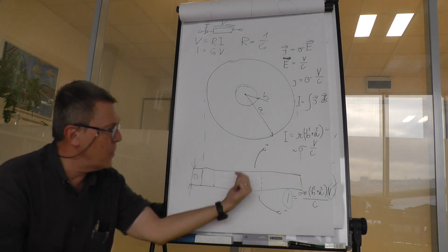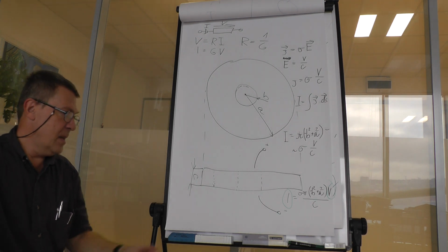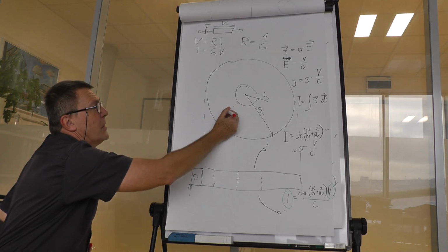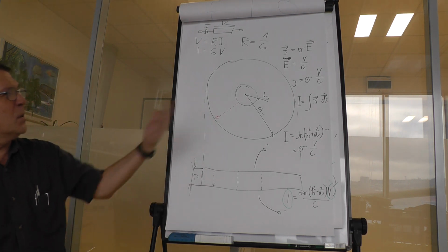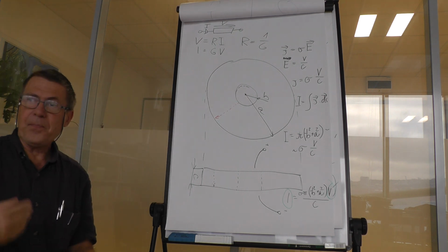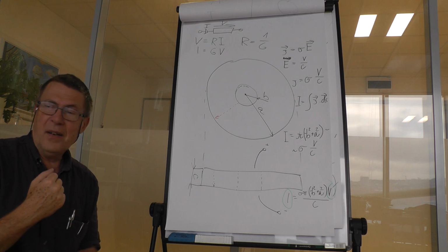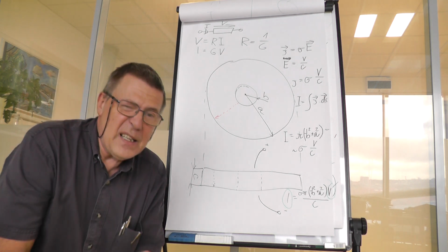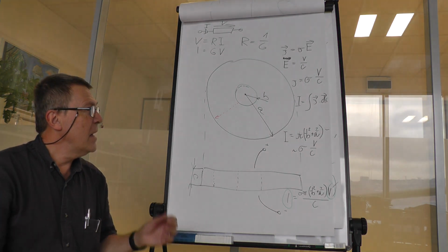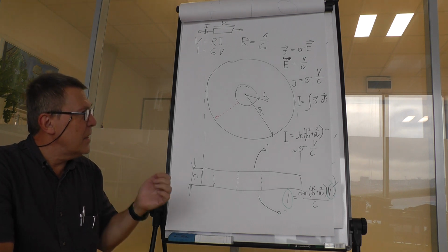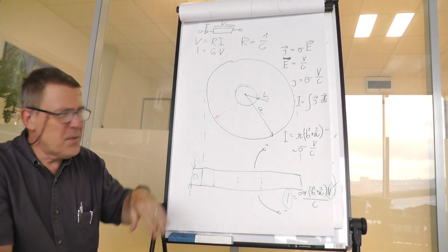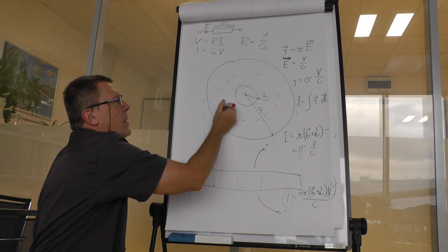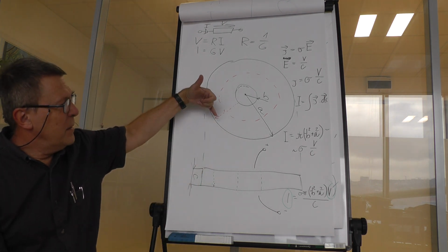So now the current would have to flow this way or this way. So that's a difference. The second case would be such that we will have a current flowing this way, radially, from the center to outside. So we will have one contact here and the other here. And in order to establish the value of this resistor, we would have to use integral calculus. In fact, this is why integral calculus has been invented. I have to tell you that the most used trick, that is, we will have average cross-section somewhere here and use average field strength, will not work.